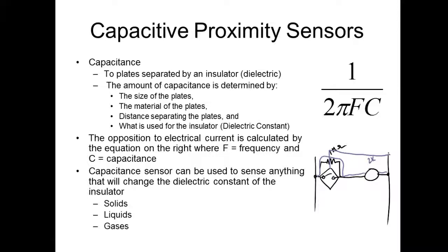They're called solid state because the circuits that generate it require so little current that they'll pick up through the other devices. So even if I put a contact right there, now it's not working, but as soon as that contact closes, then it's ready to work, right? So you can do ands with this thing. It's no big deal. They power up through there. So these are usually two-wire devices.